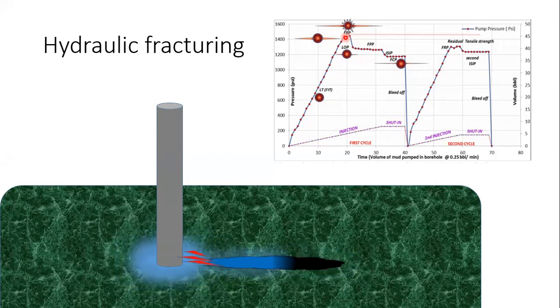From this point onwards, you can see the space over here is high. The volume of this fracture is more than the volume of the channel that was generated by perforations. Because of that, the injected fluid pressure will be less than the pressure of the fluid flowing through this empty space. Because of that, the pressure drop from FBP can be observed. This FBP is the point where the fracture breakdown is generated. After that, the fluids will move smoothly into the empty spaces of the fracture, making the pressure get reduced.